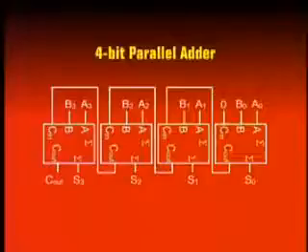But before we look at the solution, let us just revisit that 4-bit full adder, and let's see the propagation of the carry from the first full adder to the last full adder. Consider the 4-bit parallel adder. The two 4-bit numbers A and B are applied simultaneously to the 8 inputs of the 4-bit parallel adder. Now, after a delay of 50 nanoseconds, C1 would be available. After another delay of 50 nanoseconds, C2 would be available. Again, after another 50 nanoseconds, C3 would be available. And after another 50 nanoseconds, C4 would be available.